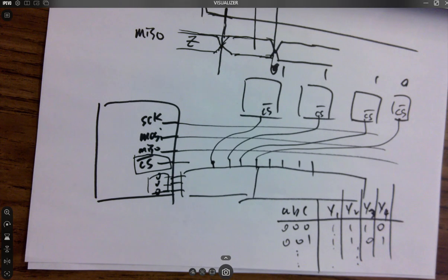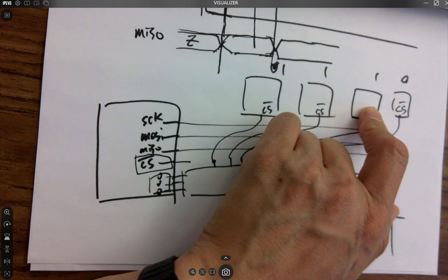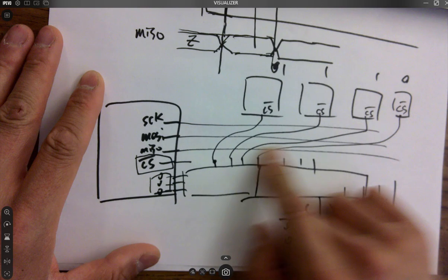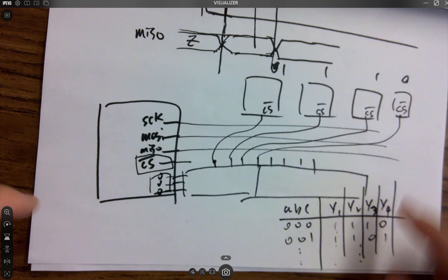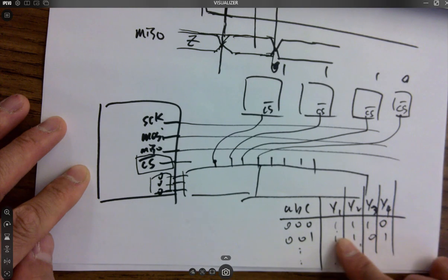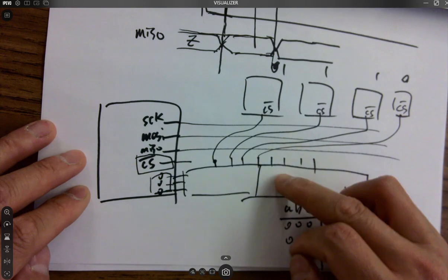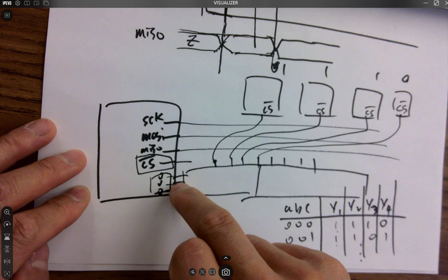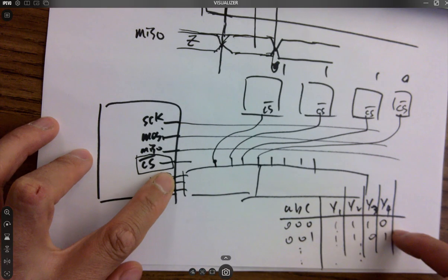No, it doesn't, because they should be different data, right? If it's the same data, why do you need 2? Right? So you need multiple sensors. They are definitely sensing different data, and then your MISO line will be different. So yeah, every time only activate one, so it has to be the 0, shifting the 0 bit by bit, and eventually design the decoder over here. Right? It could be a combinational logic, or if this is a microcontroller, you could write C code to output these patterns by GPIOs.